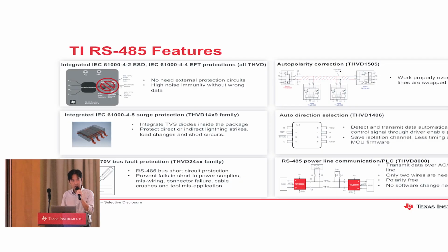But in addition to the standard RS-485, our RS-485 device product offers some additional features, as you can see in the slides here. We have integrated ESD or EFT protection. We have integrated such protection devices. We have a high voltage burst fault protection device family. We have auto polarity correction device and auto direction selection device.